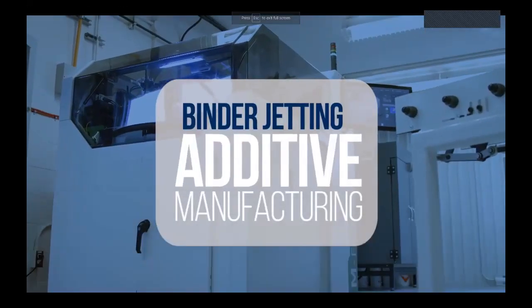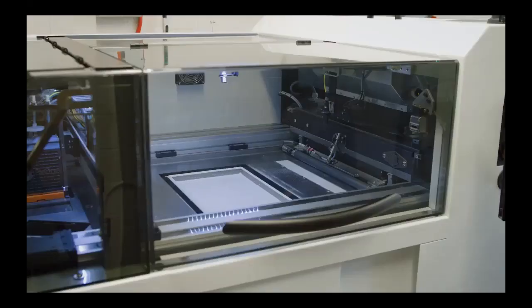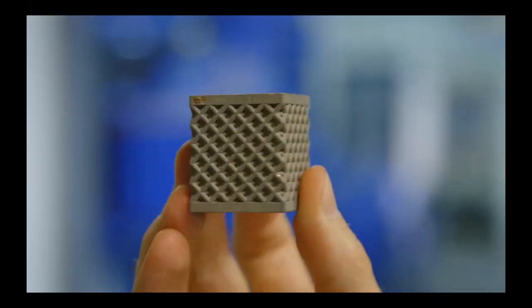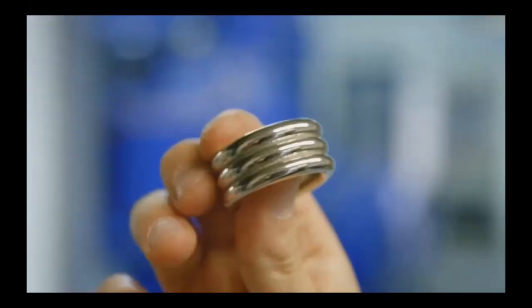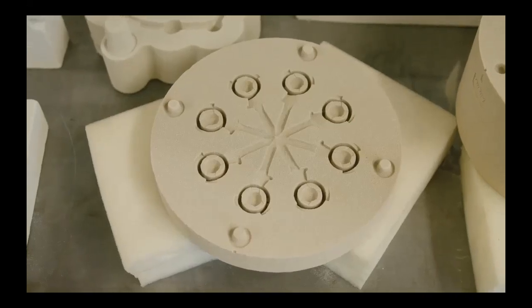Binder jetting additive manufacturing is a process inspired by the technology of inkjet printers. In this process, a liquid binder is selectively deposited on a powder bed with a print head. It is a growing process that allows the production of parts for the manufacturing, medical, and dental industries. This technique enables the production of metallic and ceramic parts, as well as sand molds for castings.